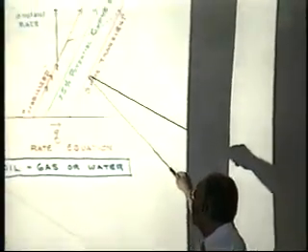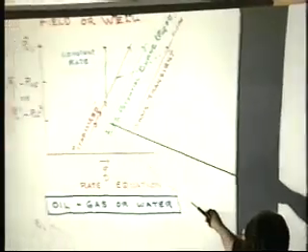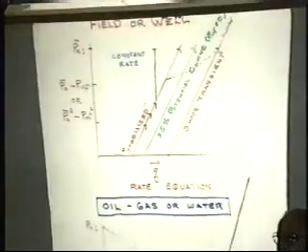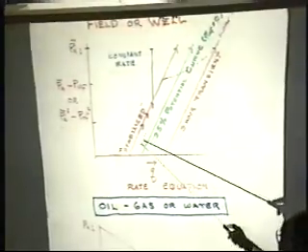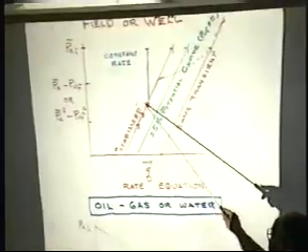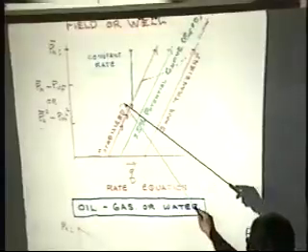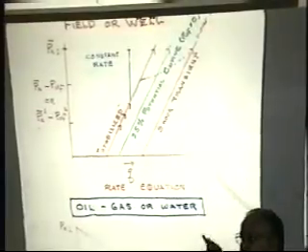I show on here what we normally plot for gas wells. We plot the transient data, and we can also demonstrate the pseudo-steady state data: there's a shift with time of the back pressure curve from a transient period to a pseudo-steady state period. When you get into pseudo-steady state, the back pressure curve is fixed. With depletion, you come down, you just trace up and down this curve.